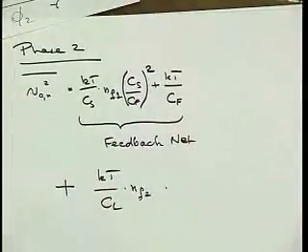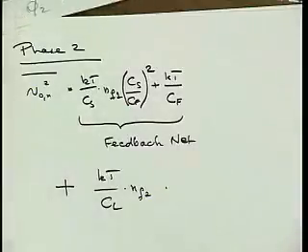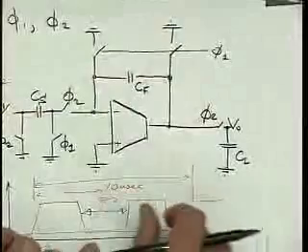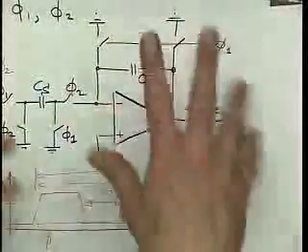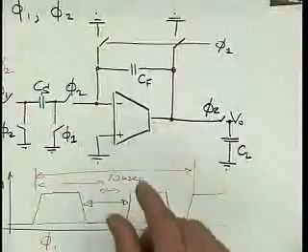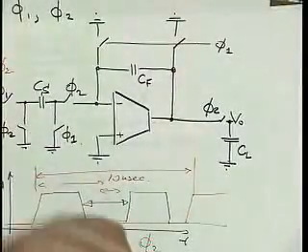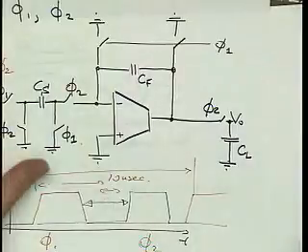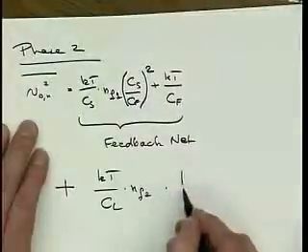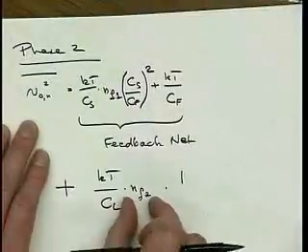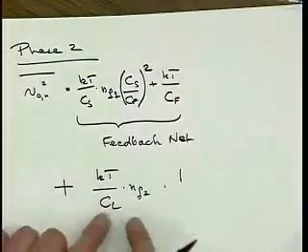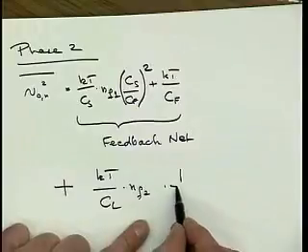And then, remember the large example at the end of our noise lecture? It looked at the case where we actually have feedback around the amplifier. During phase 1, of course, the feedback is kind of broken, but during phase 2, the situation is precisely equal to the situation that we had analyzed in that example earlier in class. I remember what the result was: kT on CL times a factor that included the fact that we used the cascode and so on. Here we don't have a cascode, we have something else, and we just call that NF, and the value is in your homework.